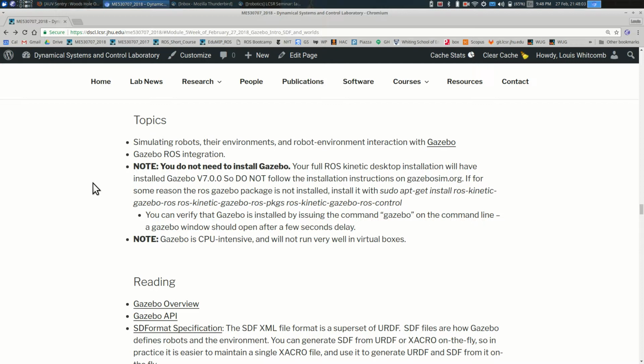Yeah, so you need to have absolute corrections to the vehicle. And you can do that. There's a couple of different ways that you can do that acoustically with time of flight, acoustic ranging. I don't have time to go into all the details, but there isn't any silver bullet for underwater vehicle navigation. You end up using a variety of sensors. And X and Y are the hardest things. I've spent a good part of my career essentially working on various aspects of that problem.